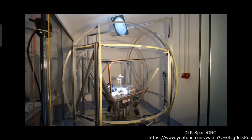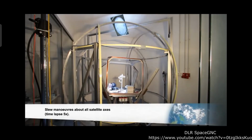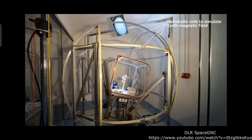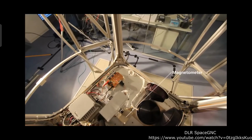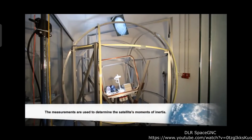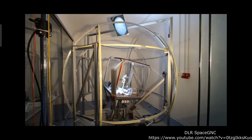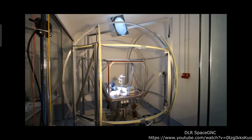If a reaction wheel spins faster, because the total momentum must stay constant, the spacecraft angular momentum must automatically decrease to compensate. The vector increase in the reaction wheel's momentum must exactly equal the decrease in the spacecraft momentum to keep a constant total. To conserve momentum, the spacecraft must either slow its rotation or start rotating in the opposite direction. In either case, the spacecraft attitude has changed simply by spinning a small mass faster inside. Two reaction wheels can deliver precise control of spacecraft attitude in all three axes.